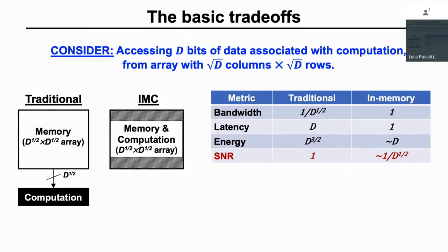In terms of energy, here I have square root d access cycles, where I have square root d scaling of each bit line, and I have square root d total bit lines. So I have this power 3 over 2. Over here, once again, I have square root d scaling of my bit lines. I have square root d total columns. And so here, the energy only scales as d. So it's that power d to the 1/2. That's really what I'm gaining in energy. So all of this looks good.